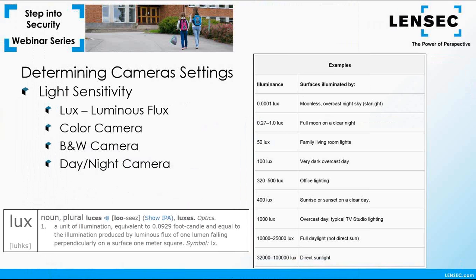This is why day-night cameras were developed. A day-night camera uses a color image in the day. When lighting conditions change, the camera light sensor will detect the change, and the camera will switch automatically to a black and white image. Cameras will typically achieve this function using digital day-night, a firmware feature, or they may have a mechanical cut filter that provides true day-night clarity.